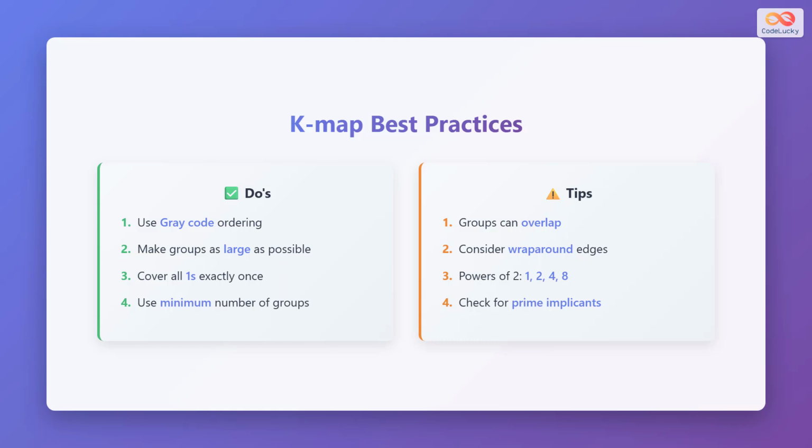The sizes of groups should be in powers of 2, such as 1, 2, 4, or 8. Check for prime implicants, which are the largest possible groups that cover at least one 1 that is not covered by any other group.